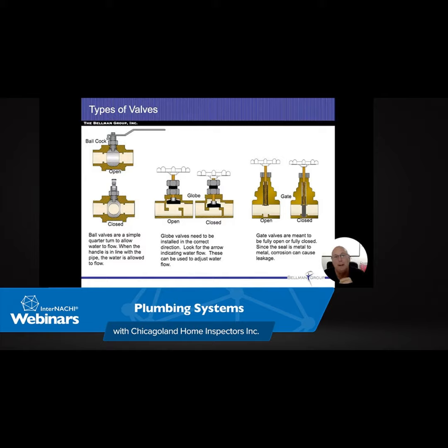And we're going to talk about a centrifugal pump versus a piston pump. Shallow wells, when we're pulling water out of it, that has to be more of a piston or a primer type pump. Where deep wells, we can use a centrifugal pump, so it actually pushes the water. It doesn't actually draw the water out. And I'm going to wait till I get those drawings up to try and explain that one.